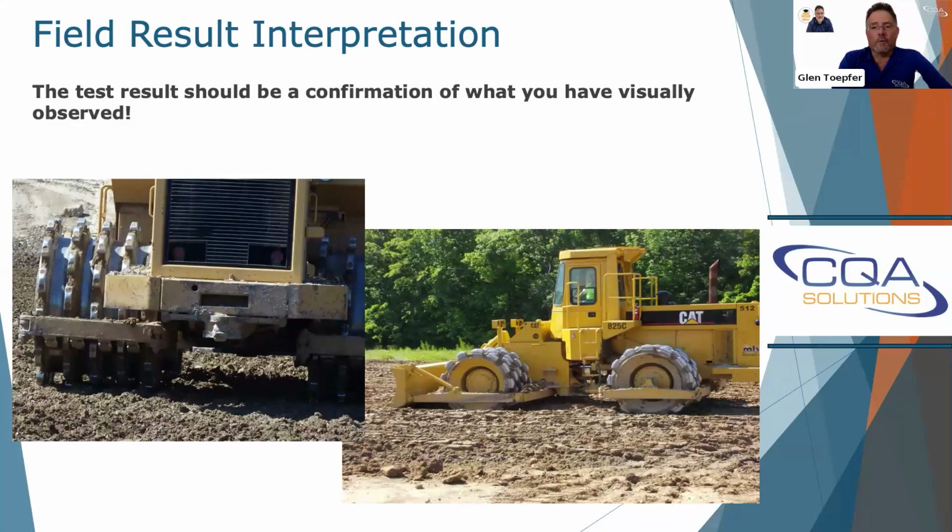One of the biggest takeaways I want to leave you with is this one here, your field result interpretation. Your results should always verify what you're visually seeing. If you have a compactor rising up out of the soil like this one in the left photo, and your test results are failing, there could be an issue. If you have the proper moisture and the test is failing, there's probably an issue. Likewise, in the photo on the right, if that one is passing, you probably have an issue because the compactor's as deep as the cleats are. So you don't want that.